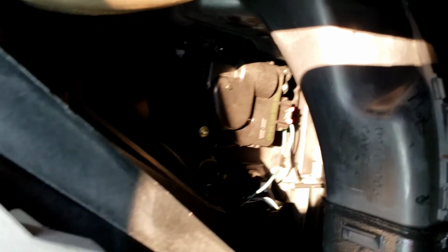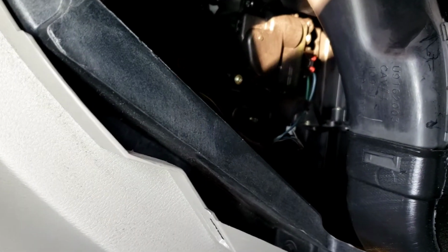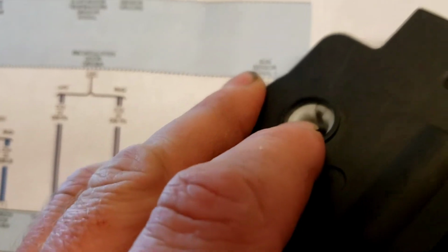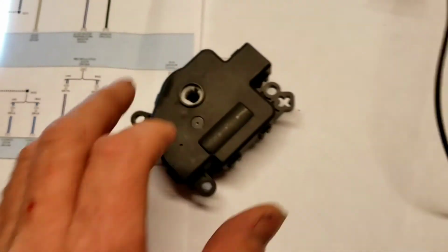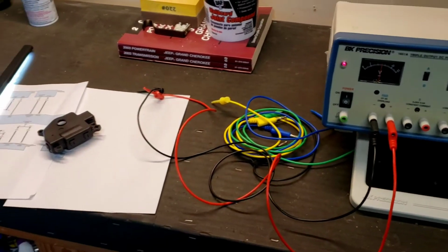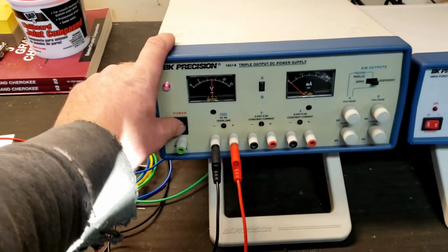All right. So I got the new one in, bolted in, and the wire harness. I didn't even check the voltages going to the wire. I knew it was a bad actuator because I did some bench testing on it with my DC power supply. And there's 2 things I noticed. One, if you look real close, it's cracked there, so it's kind of slipping in there. And also, I hooked it up and gave it 5 volts and reversed the polarity, and it was intermittently moving with my power supply. So I knew that was the problem.